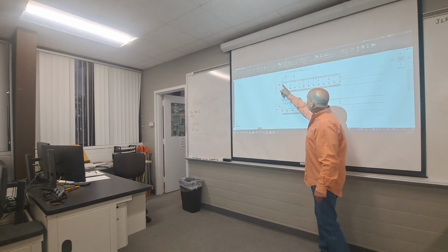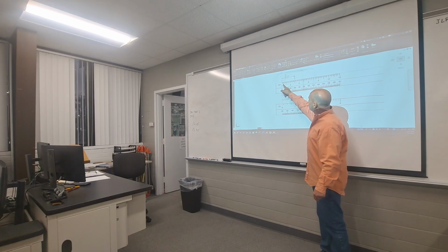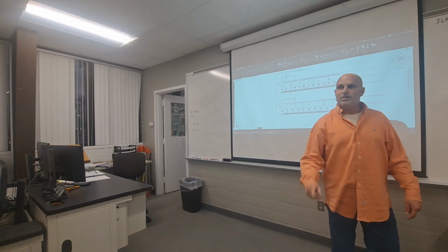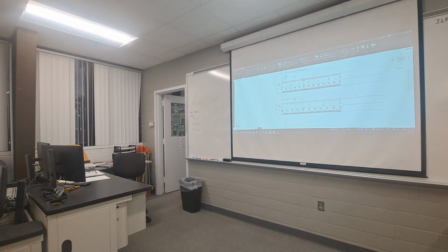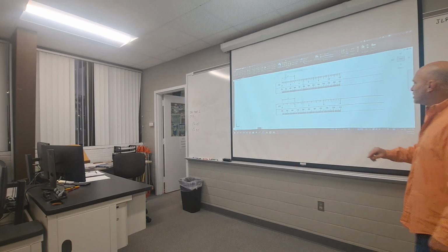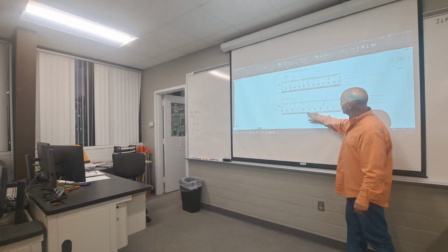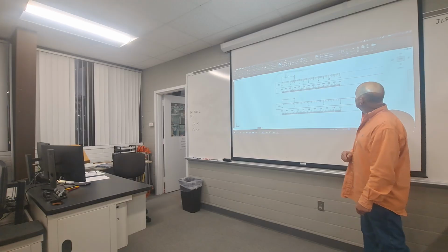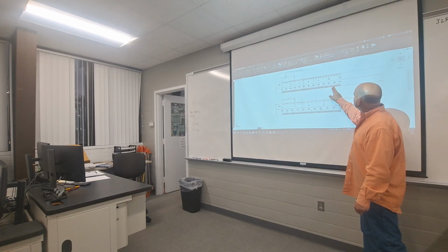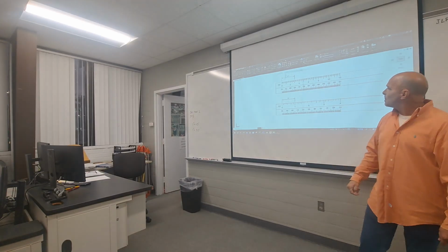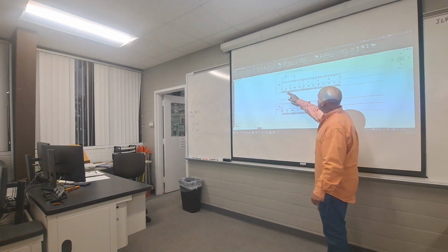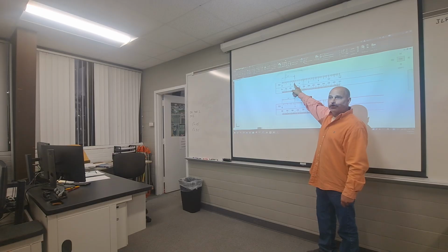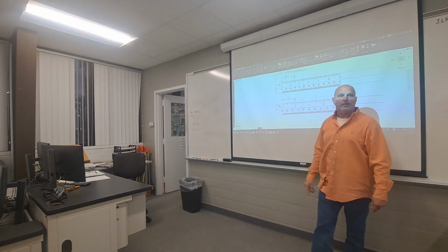The next thing is that each one of these little lines and medium-sized lines and longer lines, each one of those lines represents a distance of 1 foot, no matter which scale you're looking at. So if you're looking at some of these scales, you can see those little dashes are real tight together. That's okay, I think they still reference 1 foot each. See, nope, right here, made a liar out of it. So if I were to come up here on the 30 scale, same thing. I could measure from 0 to what would be 30 feet. They don't have the 3 on there.